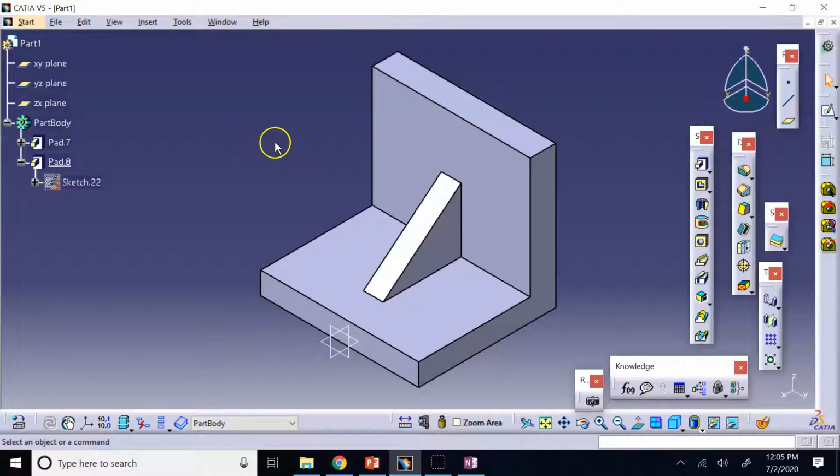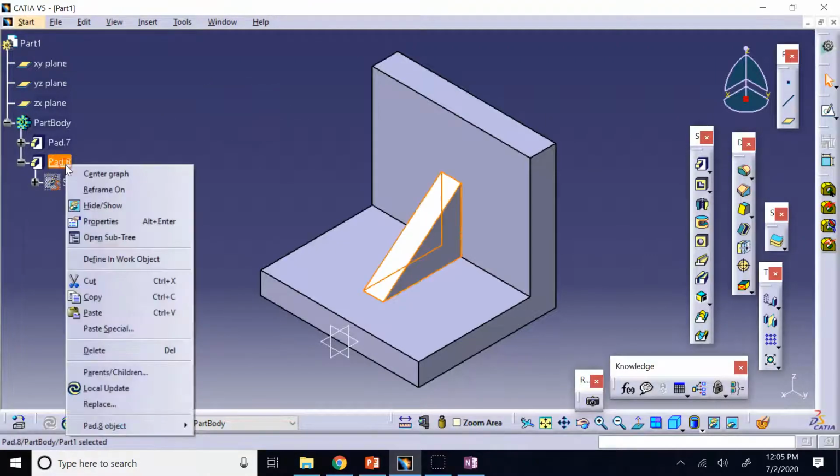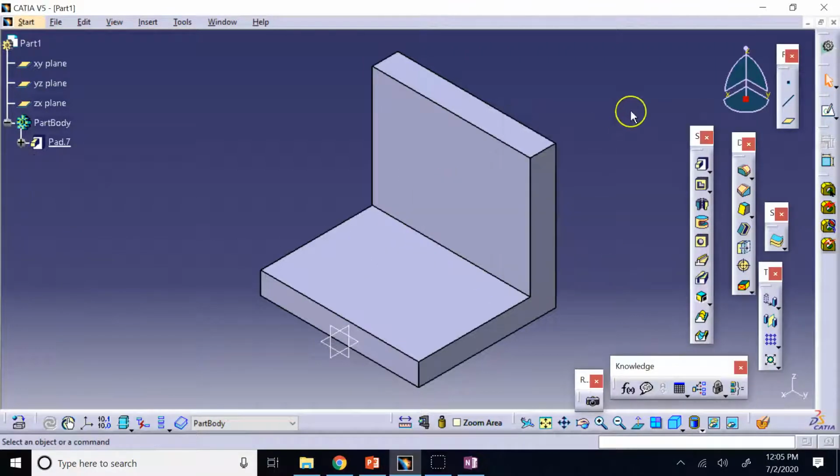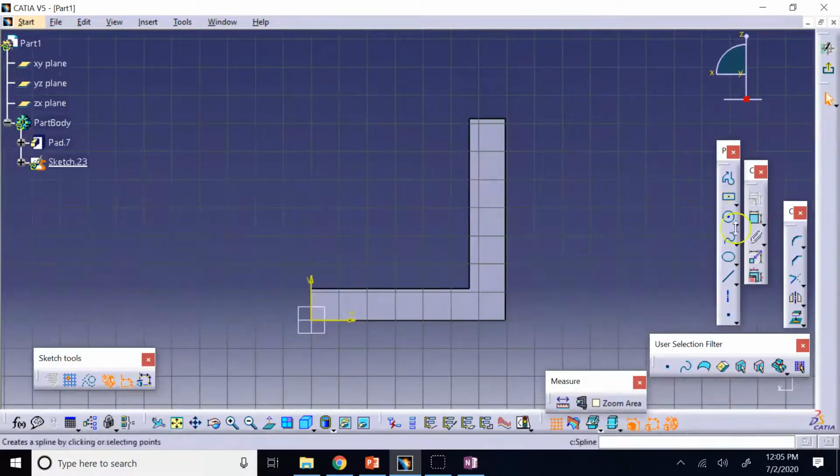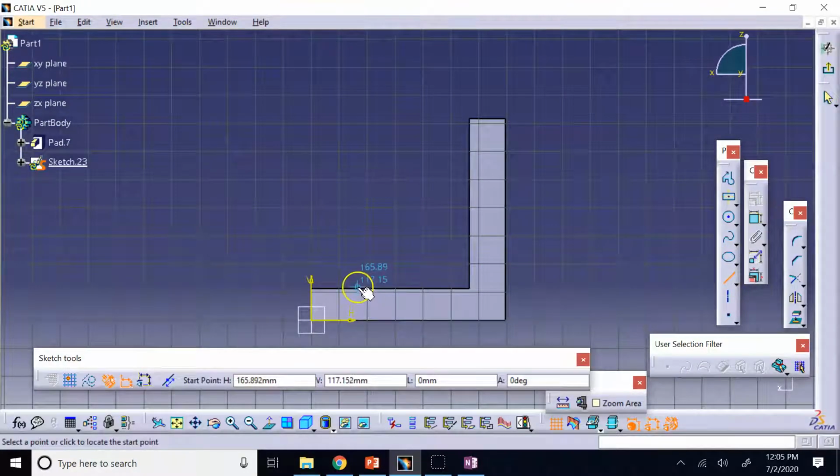The other way to do it instead of this is, all you need is just this inclined edge of the profile. The rest of the edges are the vertical and horizontal. CATIA will figure it out. What do I mean? So you go on this mid plane again, but you don't need to draw the whole triangle. All you need to draw is a single line like this, which goes from here to here.